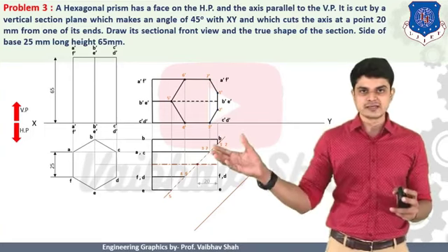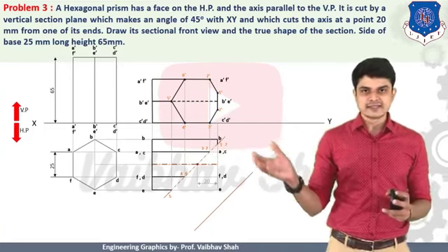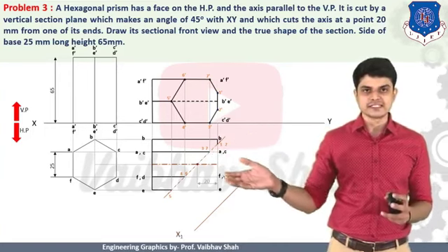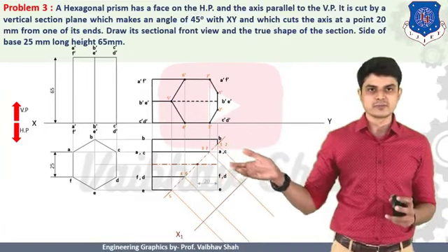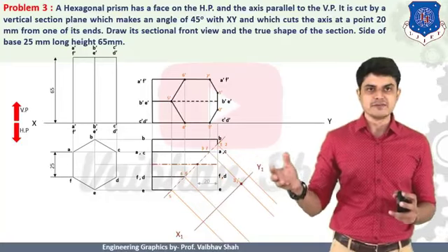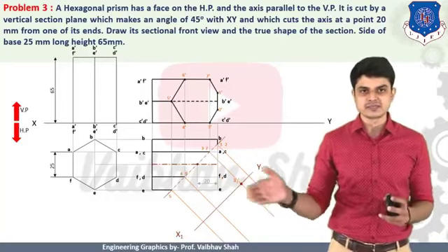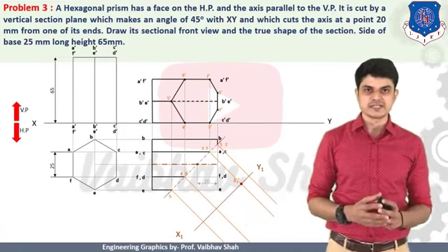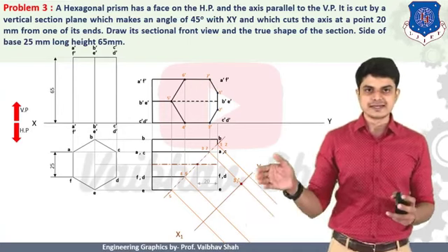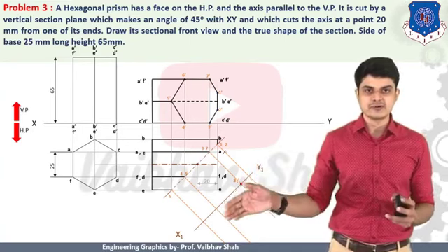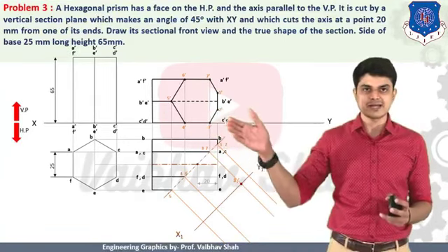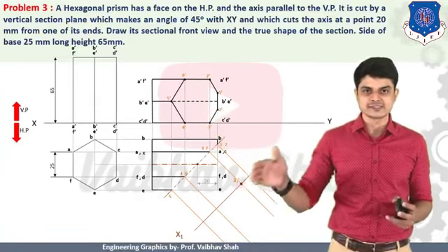So we should be drawing a line parallel to this line like this. Therefore, we should draw the perpendicular lines from each and every point like this. Then we should specify the points with respect to these parallel lines onto this image in order to create your true shape of section. So let us consider this as your XY line now. So this is your real XY line. This XY line is now placed at certain angles. So this is now your XY line.